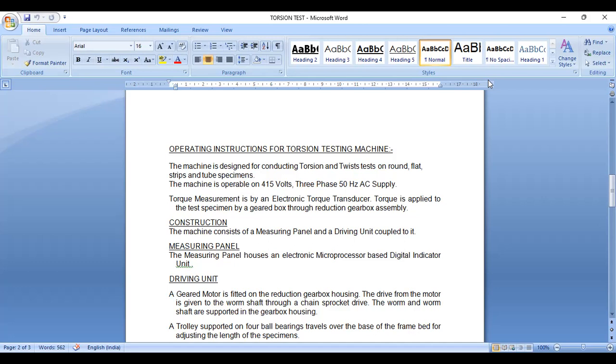So you should have a unique test piece, manufactured separately by the same process as the original member under consideration, so that you can check the impact strength, or the torsion strength by checking the torsion stress of the test piece, etc.